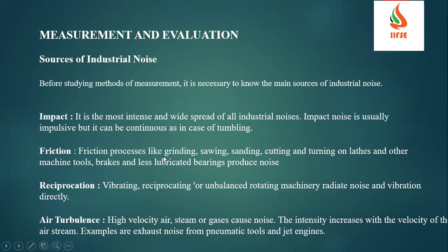One is friction, a friction of processes like grinding, sawing, sanding, cutting, and also turning of lathes, machine tools, brakes, etc. Whenever two metal parts are in contact and interacting with each other, it will generate friction. Then reciprocation, vibrating or reciprocating or unbalanced rotating machinery, like any gearbox, shaft or couplings. Then air turbulence: high velocity air, steam or gas causes noise, like any gas leakage or steam leakage. The intensity increases with the velocity of the airstream. Examples are exhaust noise from pneumatic tools or jet engines. So the leakage of air or steam will also generate high amounts of noise.